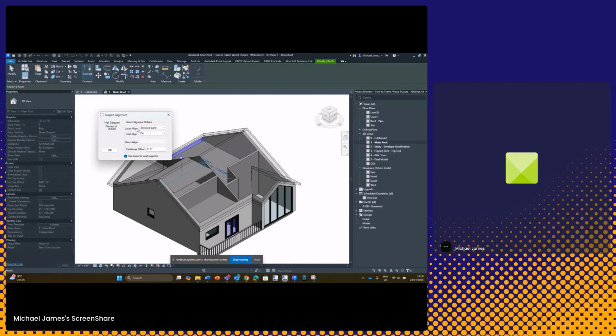So as I've selected a wall, you can see we've got two alignment options, structural layer, which is taking into consideration the core layer within the wall. We can align to parts of the core layer, or we can take into consideration the whole wall thickness. I'm going to say the whole wall thickness for today. And actually, I'm prone to change my mind, so I'm going to say structural layer, and I'm going to align to the far side of the structural layer. Okay.